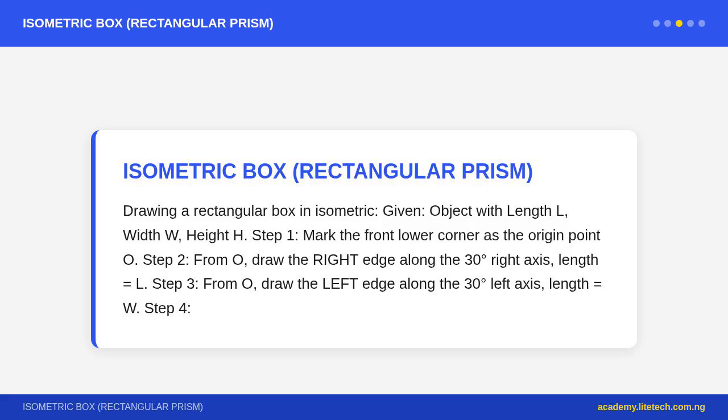Adjust radius so each arc starts and ends exactly at the midpoints of the sides. Step 5. The 4 arcs together form a smooth ellipse, a reasonable approximation of the true isometric circle.